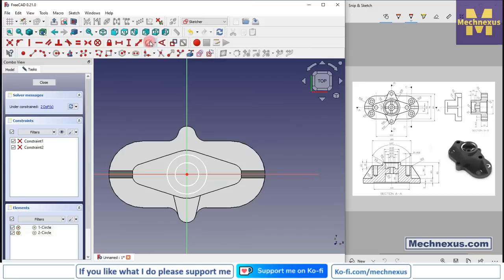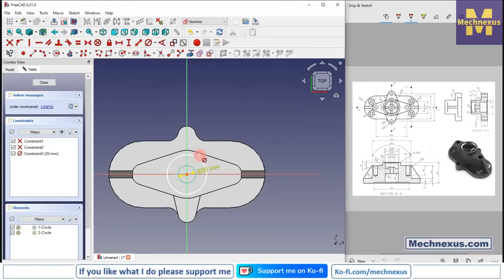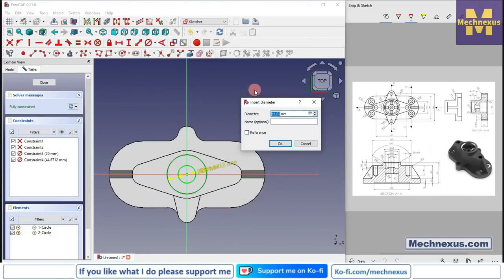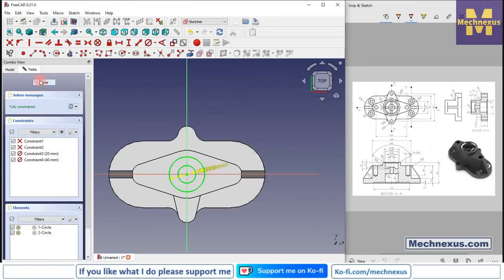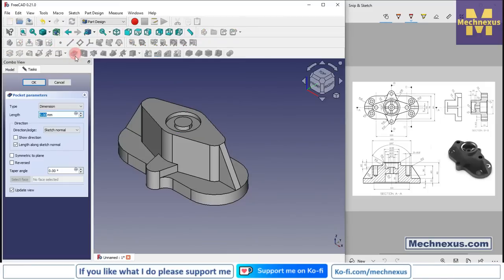Inner one is of diameter 20, and here is of 40, and click on close. And here we will create a cut of 20 mm, so click on extrude cut, and here we will give the depth of 20 mm, click on OK.